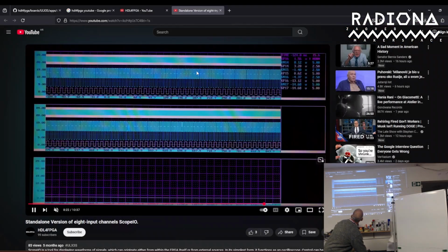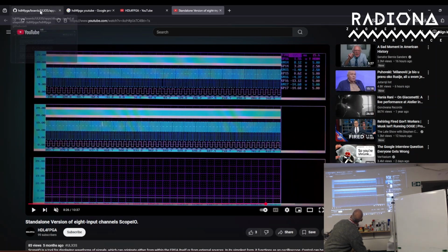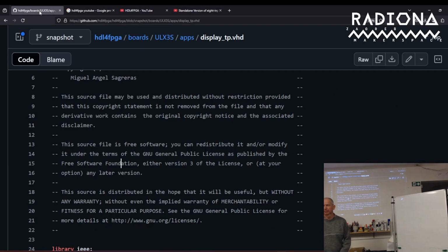Of course, the FPGA vendors are pushing their own embedded logic analyzers. In the case of Lattice, I can confirm it never worked at all. And in the case of Xilinx, it works, but it will crash your running frequency significantly and has significant limitations. So yeah, that's the idea. Use this as an embedded analyzer where you have the full control.